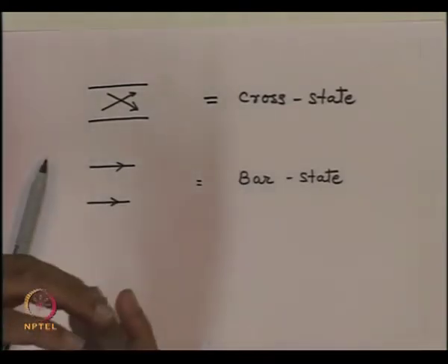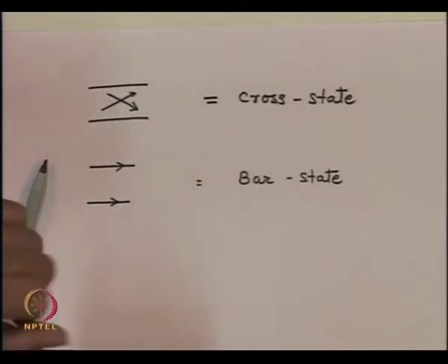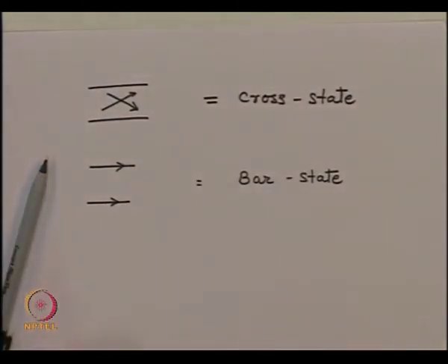So, if we take the directional coupler and make this on an integrated optical device, then by applying the control signal, I can put the connection into cross mode, or by not applying the signal, you can put the signal into the bar mode. Once you have this basic configuration, then we can build a complex switching network around it.